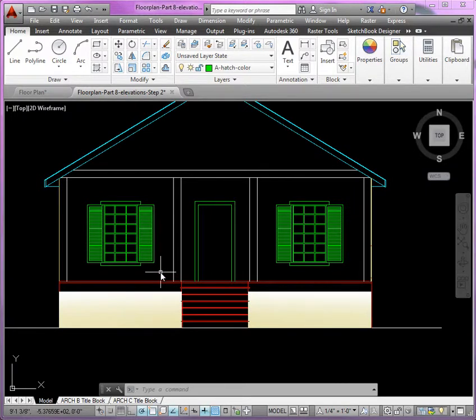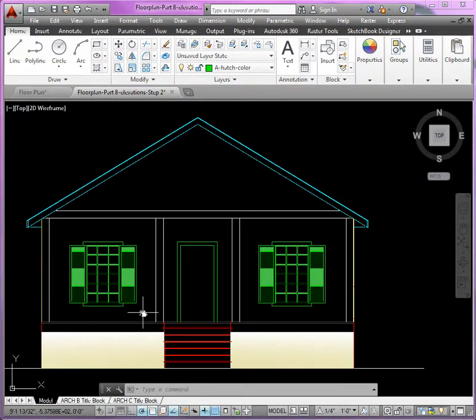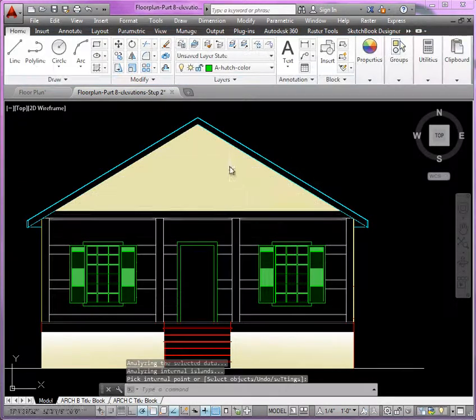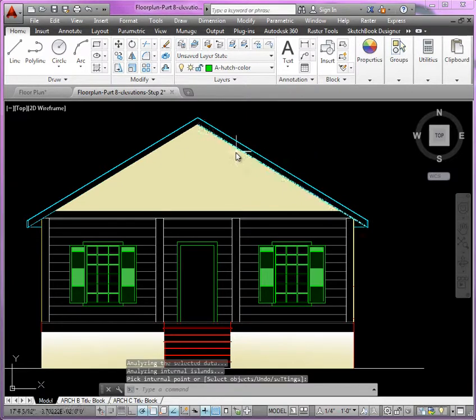Let's take a look at another hatch gradient here for the walls. Let's make this like green, like a sage green, okay? So here, what I'll do, and I want to try to incorporate light here. So I'm actually going to hatch both of these a little differently, right? This is over the front facade. What I could do here is something like this. Let's go back to hatch, okay? And again, let's just place it in here. We might have to redo that.